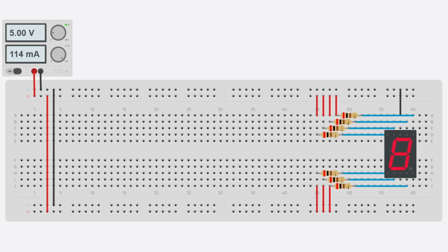So now we're ready to start by hooking up our digital inputs to drive our logic circuit. To do this, we'll be using this multi-switch on the left for our inputs. Although it's made up of 4 individual switches, we'll only be using 3 of them, because as we covered in part 1 of this video, we only need 3 bits of data to count to 4 in binary. So we'll connect each of our digital inputs to 5 volts as shown. This way, if we close one of the switches, the high signal will appear on the other side as well. This works fine if we just want to switch a load on and off, as you can see. But because we're going to be using these signals to feed a logic circuit, we're going to need to add some pull-down resistors.